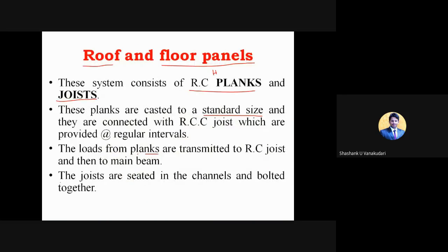Yeah, and here the joists which are seated in the channels are bolted together. In some cases when you have used steel structures, they connect with nut and bolt connections. And when these concrete members are fixed together, those RCC joists which are resting on the wall panels will have certain connections between them, like they are bolted with nut and bolt connections, and then grouted with some adhesives.